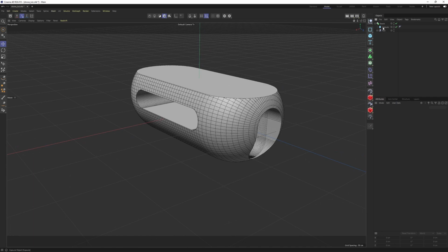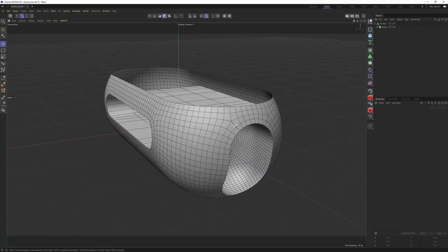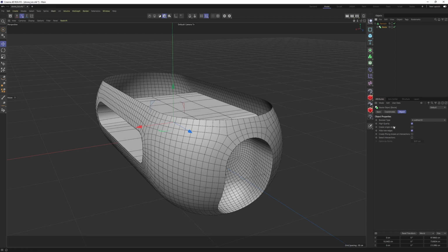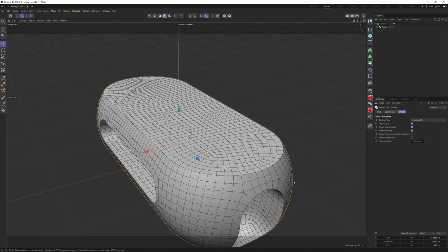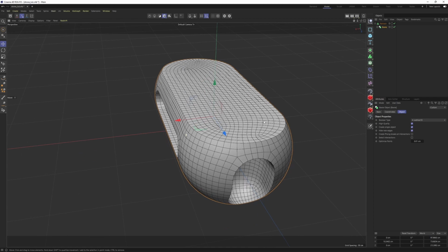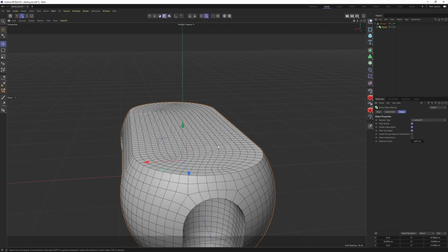Now it's time to add our new magical generator, Z-Remesher. Select Remesh and put the bool under the remesh. Alright, looking nice, but we can do it much better. Go to Remesher. Actually, before doing anything in the settings of the remesh, I will go back to my bool and enable create single mesh and see what's going to happen. Perfect. So basically, if you enable create single object, this boolean will act like a single object and Z-Remesher will see that boolean as a single object, which will give that perfect result.